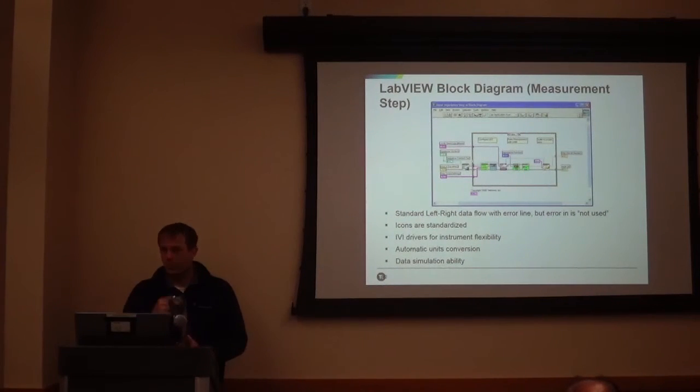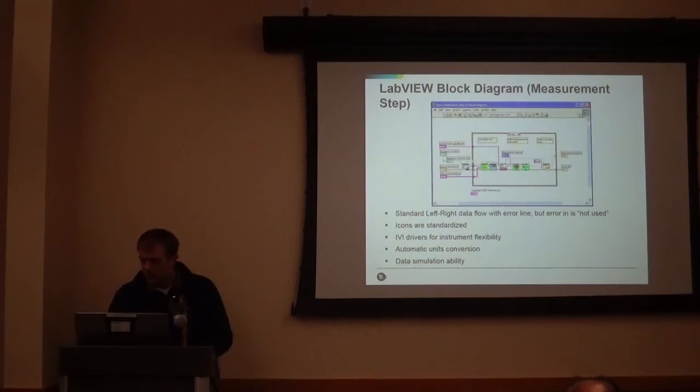Every machine that runs sequences has to have a base deployment license at minimum, and that's what will allow you to run, but it will not allow you to edit. Other license levels above that will allow editing. So if I install some higher level of TestStand, maybe I have to remove it and put a base there. Well, TestStand itself can stay on the computer, or you can create a TestStand deployment image. It's how you license that particular computer that lets you edit or not edit sequence files. Maybe that computer has a higher level license, that's why I'm able to edit it.